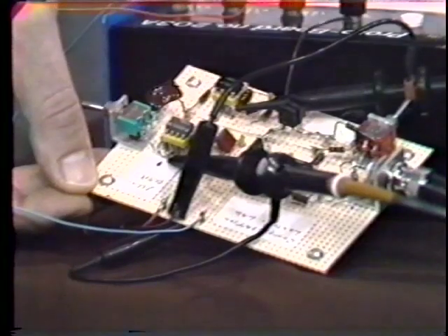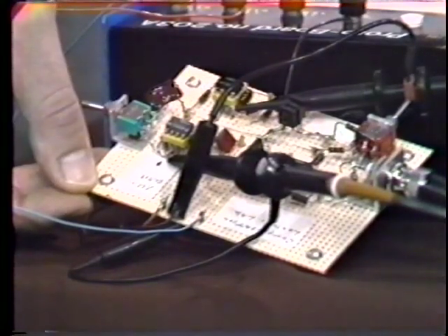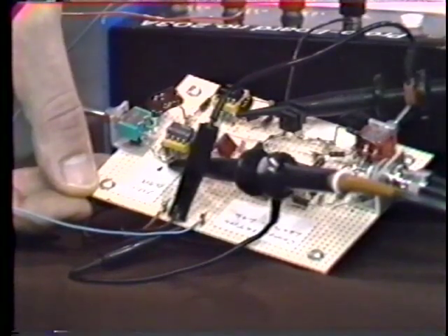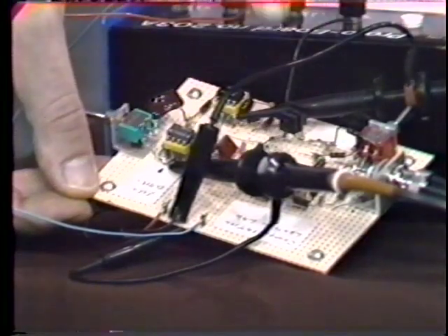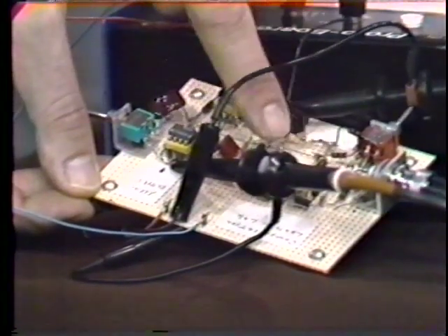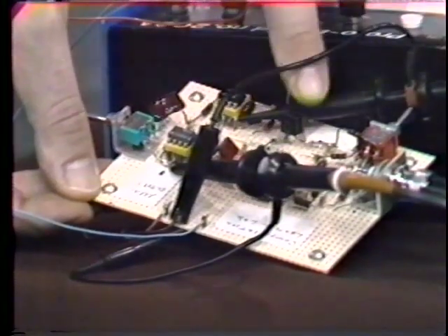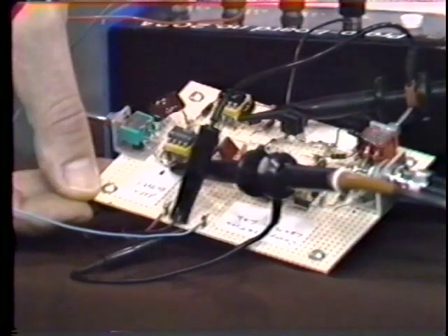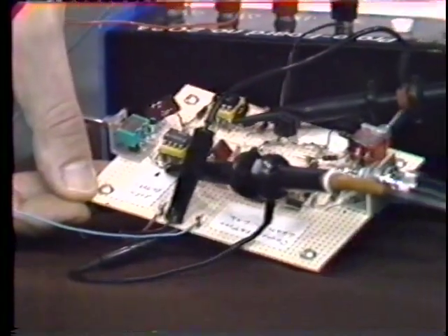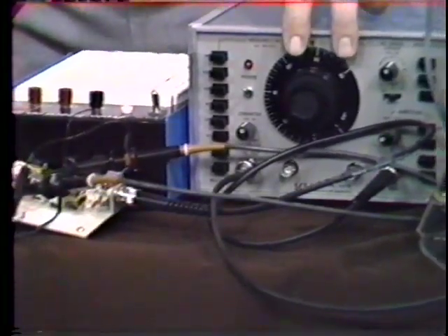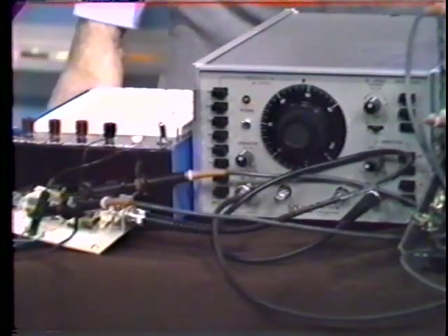And we drive our pseudo amplifier, which is connected for the gain of 10 via 2 feedback resistors to give us the closed loop gain of 10. The resistors are actually in here, 2 precision resistors equal to 9R and R, down in here somewhere. We take that amplifier and we drive it with a signal from the signal generator, and we then look at the output of our amplifier with the oscilloscope.